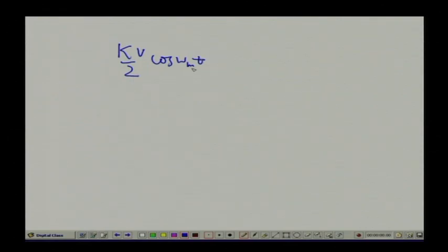So, that means we have only signals which consist only of delta f by 2. Now, the cutoff frequency of this low pass filter must be greater than delta f by 2. So, what is delta f? Delta f we have seen, f r minus f I, is coming as 33.93 kilohertz.